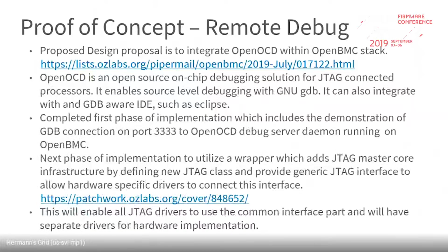But for remote debug, I sent a proposal earlier in July, and we completed an internal demo, which is the first part, where the GDB client would be running on the user administrator side, connecting to port 333 on the OpenOCD debug server.